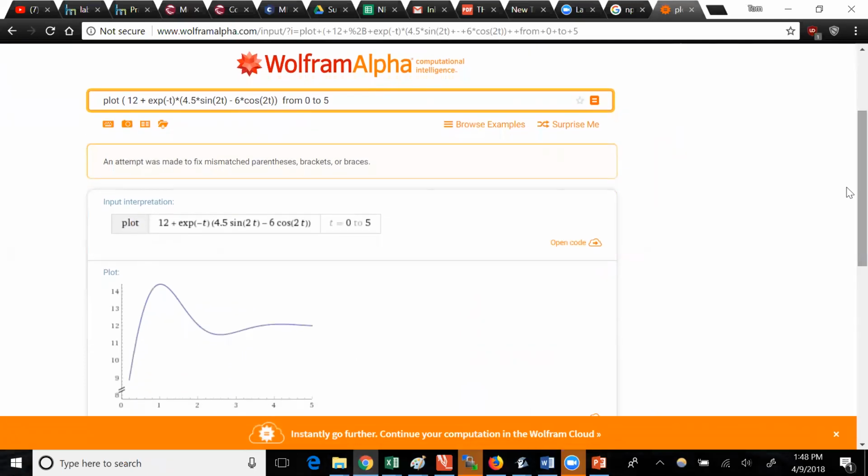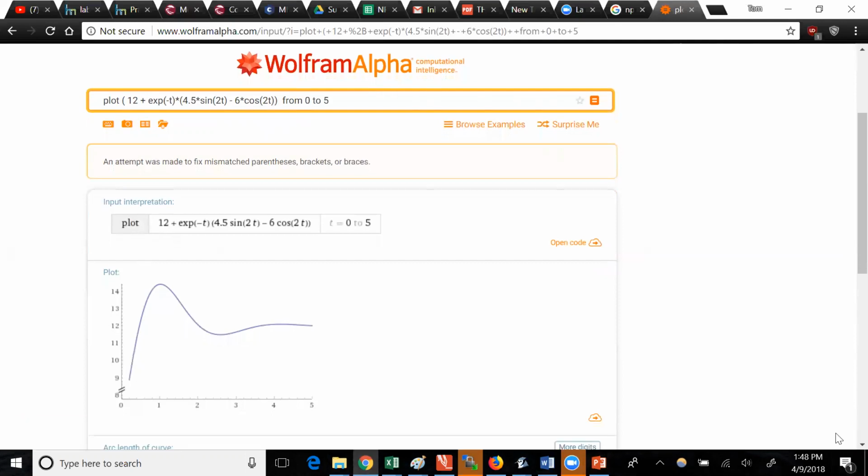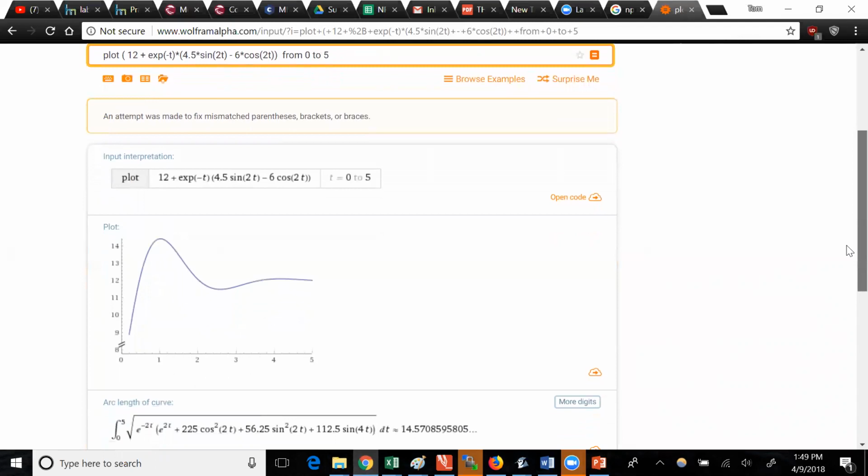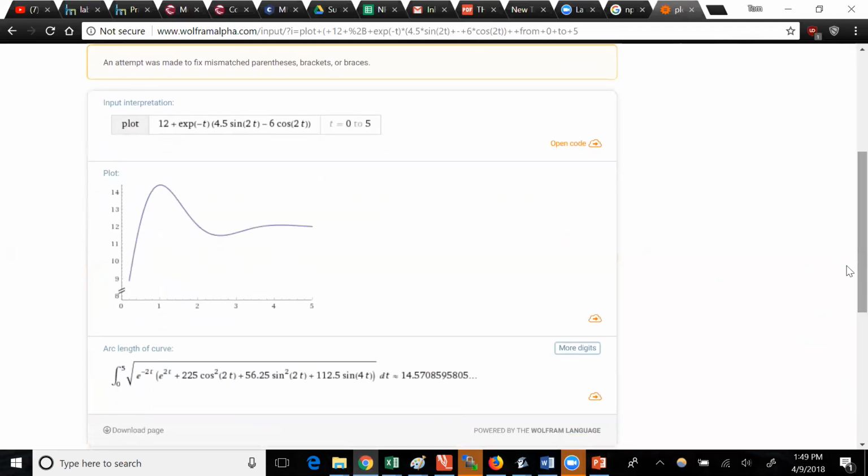And this is sort of the classical underdamped solution, right? It's a decaying exponential. It's rising up past the final value. It goes way up to 15 volts or so. And that's why you can see, if this was in one of those boost converters, you're getting 15 volts temporarily. You could be sucking that current out and charging a capacitor on the other side of a diode there. And then it drops down and steadies out at 12 volts. So that's the solution for the voltage.